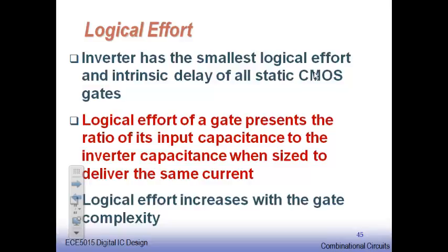So the logical effort of an inverter, with twice the size for the PMOS, that's how we had. So whatever delay is incurred due to the inverter drive would be your TP0, I told you. And similarly, when I consider some other complex gate, how big is it in comparison with an inverter? We are going to check.